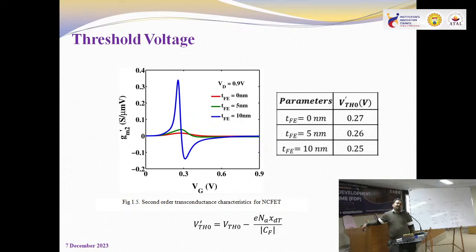No, actually, understood sir. You are asking me what is the value of dielectric thickness I have taken. Yes, actually that is not in my hand. I have used 32 nanometer. In 32 nanometer there is a set of standard specifications. So for the 32 nanometer BSIM model there will be a fixed value of dielectric capacitance. Dielectric thickness will be fixed, and the material will also be fixed.